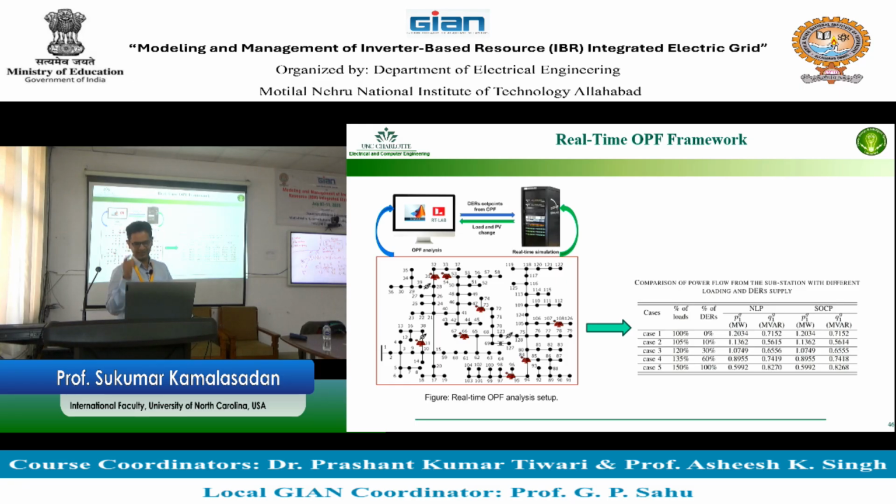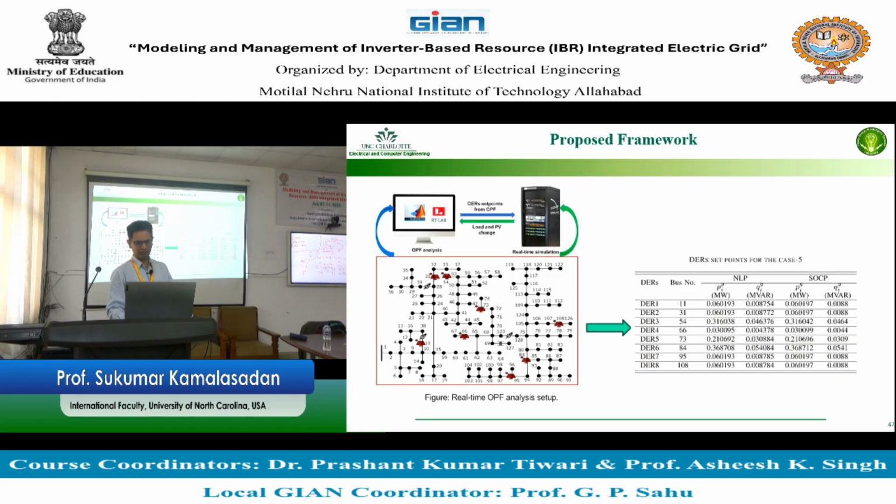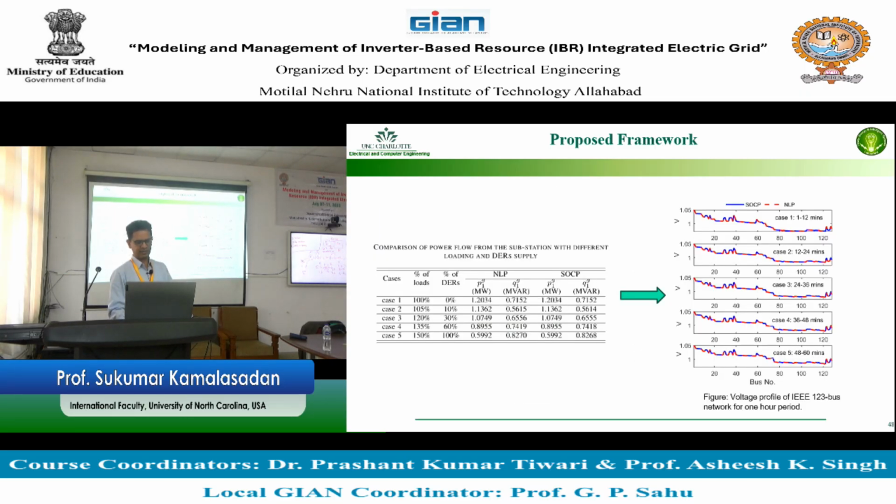So NLP and second order cone programming, you have that output coming from there, and you can look at the bus number where the DERs are connected, and set points for each of those bus numbers can be generated from there. And with that set point you can look at what will be the voltage profile on a 1 hour period if these set points are implemented.